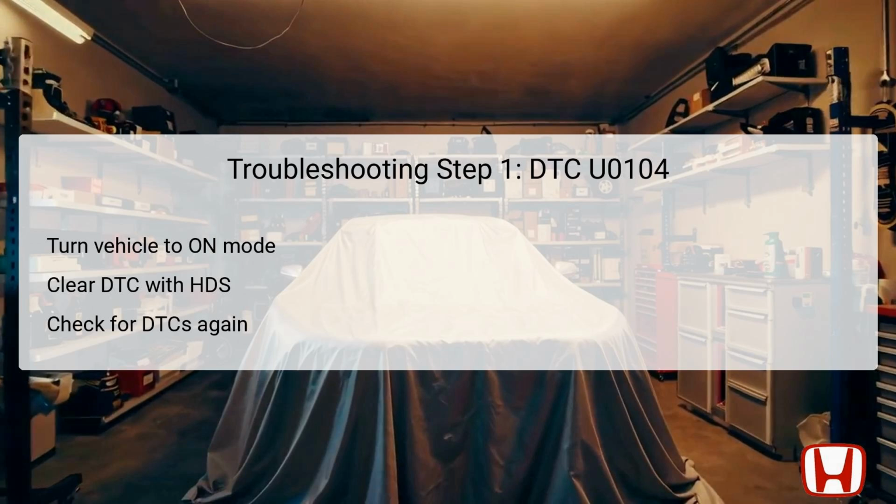After clearing, turn the vehicle back to the off or lock mode, and then back to on. Finally, check for any new pending or confirmed DTCs with the HDS. If DTC U0104 persists, it confirms that the failure is indeed present, and further investigation is warranted.